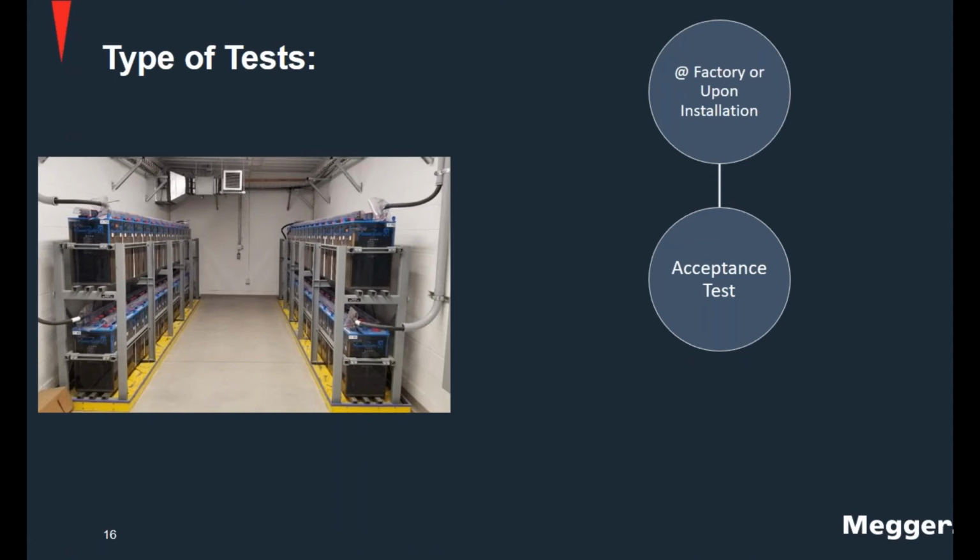When you run the test, you run it at a specific constant discharge rate and duration, and it's usually a test that you perform to verify the nominal capacity of the battery. Depending on the requirements, you may select a different rate, but it has to be very well discussed and defined with the owner and the supplier of the battery.